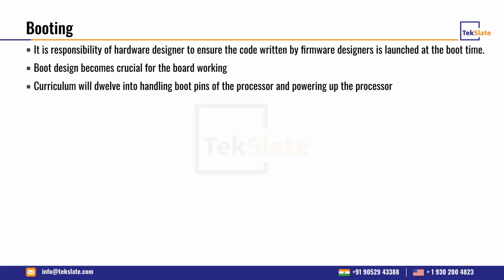As we discussed, board design is a crucial aspect. Typically, the microcontroller has boot pins. The boot pins need to be properly bootstrapped when the processor is powered up. So the board design becomes crucial for the board working. The curriculum will dwell into handling the boot pins of the processor and powering up the processor.